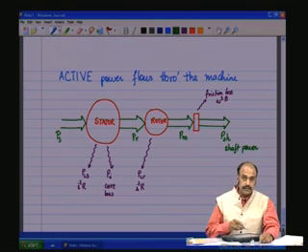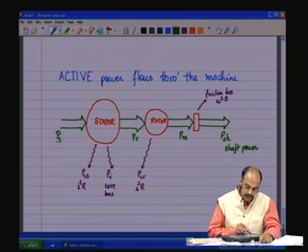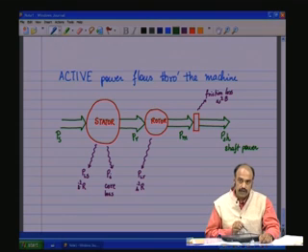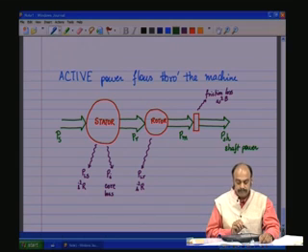So this is how the power flow diagram is in the case of the induction motor. You have the stator power PS, which is the input to the motor. Out of that, a portion PLS goes off as the stator I square R loss, and an amount PI goes as the core losses in the magnetic domain of the stator and rotor.